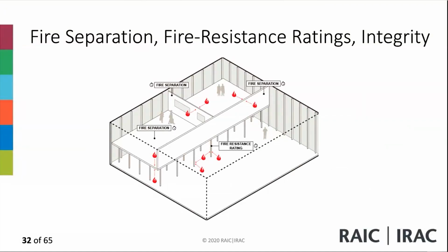This floor plan has 3 suites. Not, let's see, I'm not looking at suites. I'm telling you, it could be suites or it could be areas within the buildings that are used for separate uses. So here, let's see here. I'm not showing doors or anything, so this is not a proper drawing to show, and it's not per code. But this is just to illustrate the elements that may be considered fire separations.